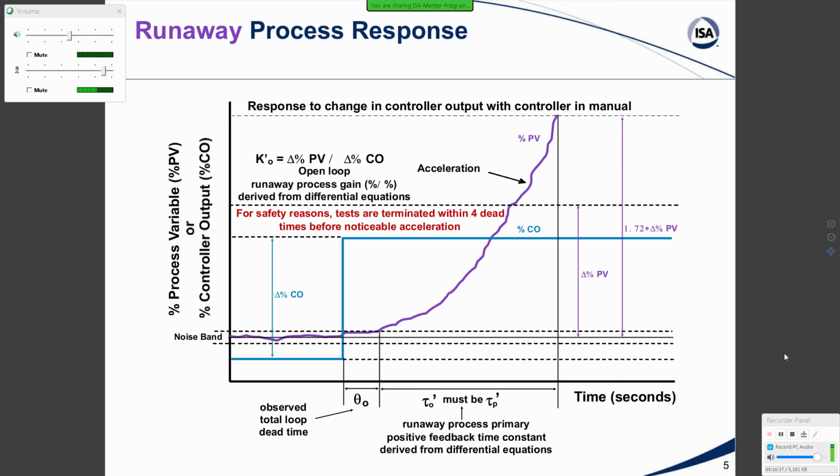And he did it only for a proportional plus derivative controller. He didn't even include reset action, and we had really good reasons why we didn't want to put reset action in there. Now you can if you do it very cautiously, but as we get into the very last of these WebEx sessions, the clue here is the way you implement integral action, the way it was done originally and the way it's still done in many systems, with the greatest capability that we're going to get into in terms of external reset feedback.